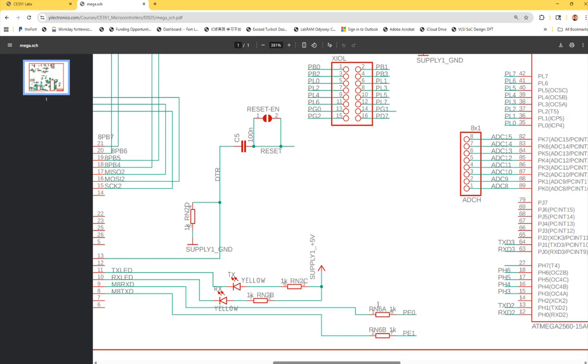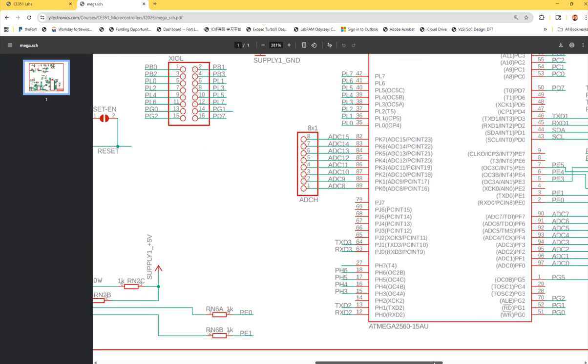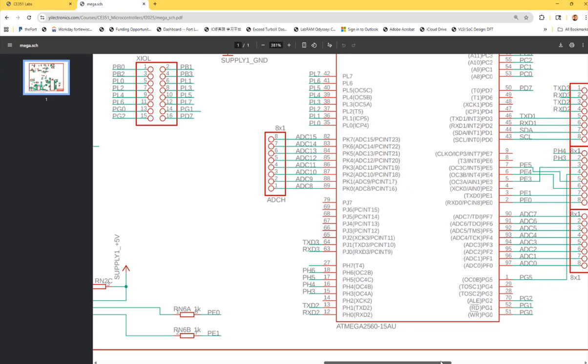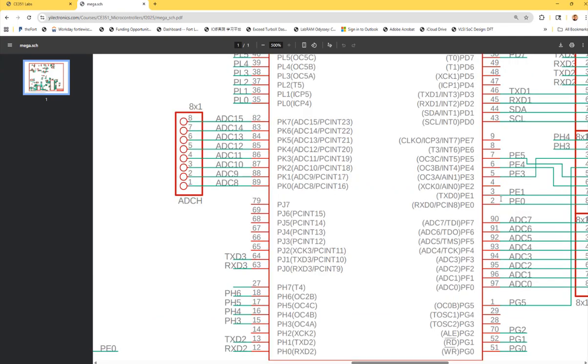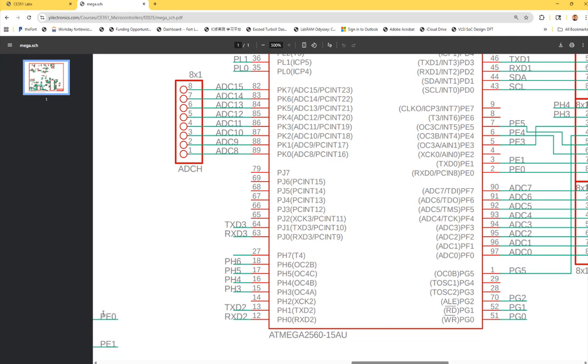and it's reaching these 2 points. It's PE0 and PE1, right? PE0 and PE1. And then you start looking for PE0 and PE1, they're over here. Okay? Eventually, these with the same name will be physically shorted together, even though in the schematic they don't physically short, but actually they are, because they have the same name. So PE0 is shorted to here, PE1 is shorted to here.